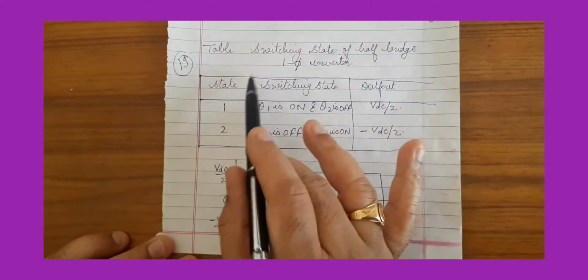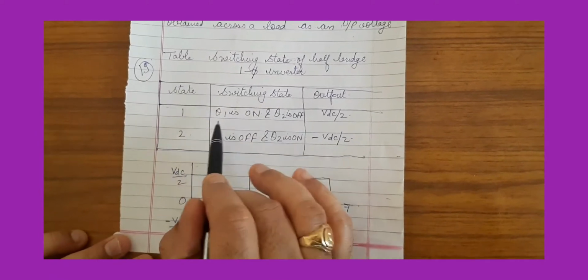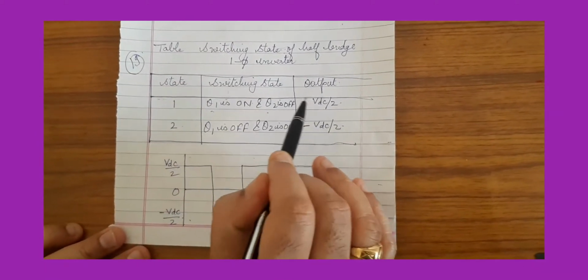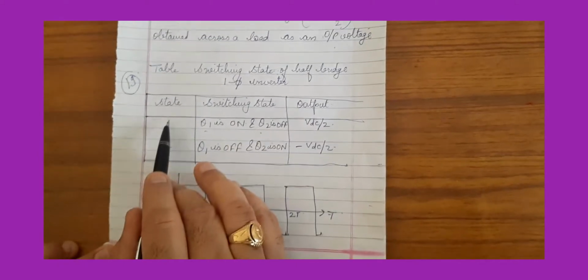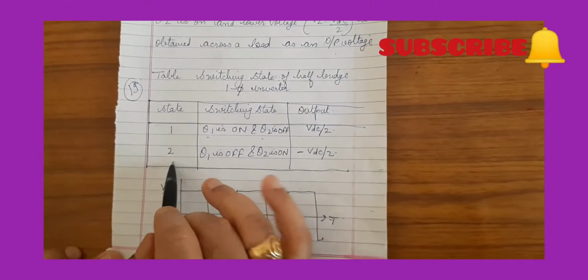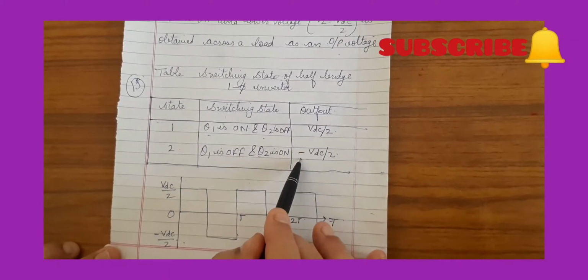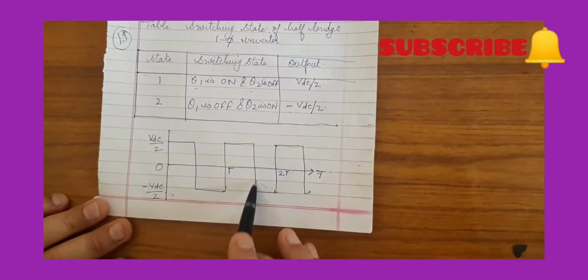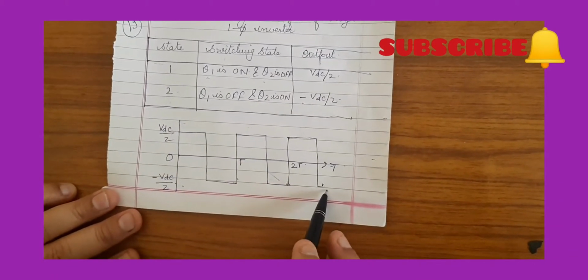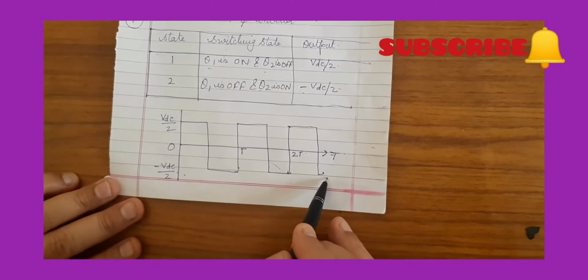Now this is the table of the switching states of the half bridge inverter. In stage 1, when Q1 is on and Q2 is off, we get the output VDC upon 2. For stage 2, Q1 is off and Q2 is on, and we get the output minus VDC upon 2. This is the waveform of the single phase half bridge voltage source inverter.